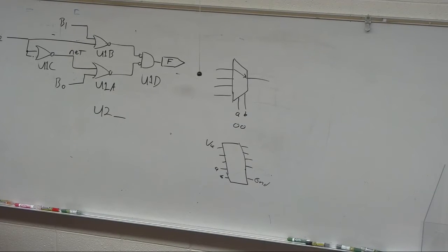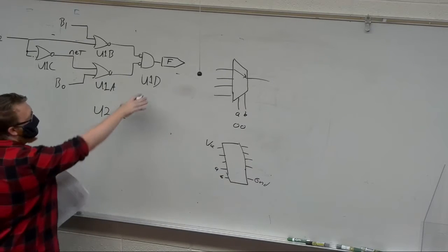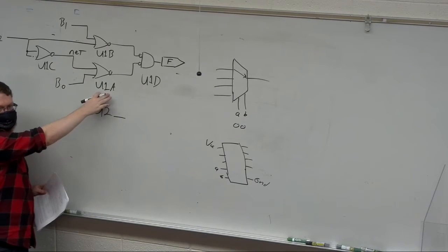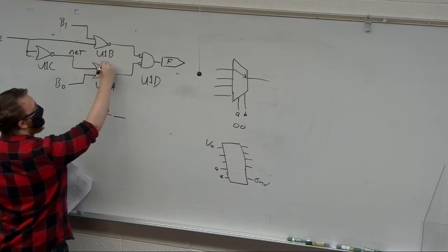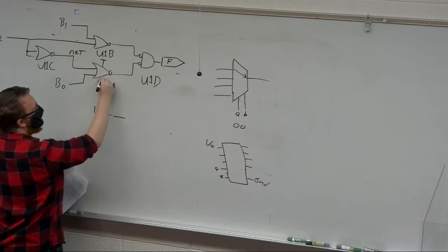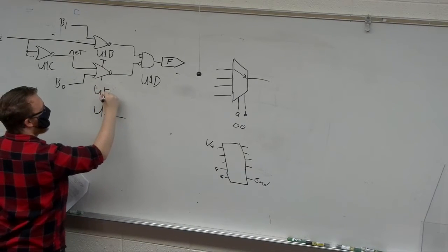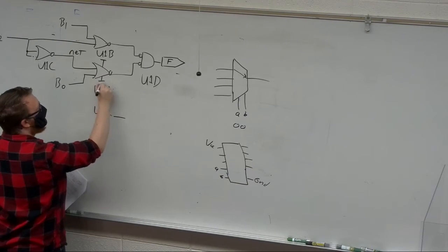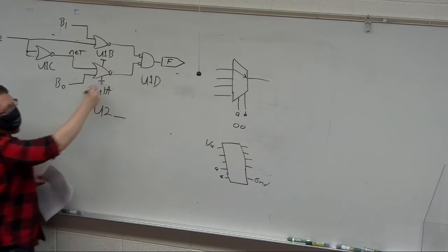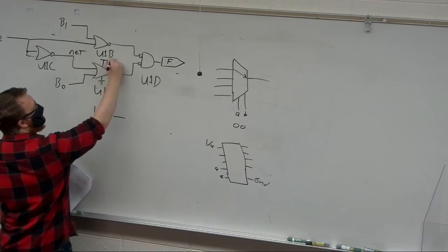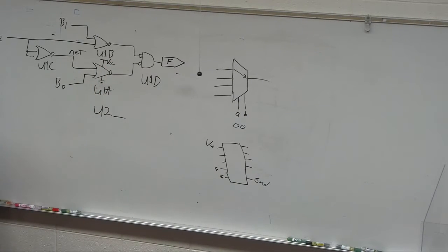So something that they'll do if you're working with a real schematic is, in the device, they would go to U1A, the first one, and they would add explicit power and ground symbols, so that you could then say this is attached to VCC.